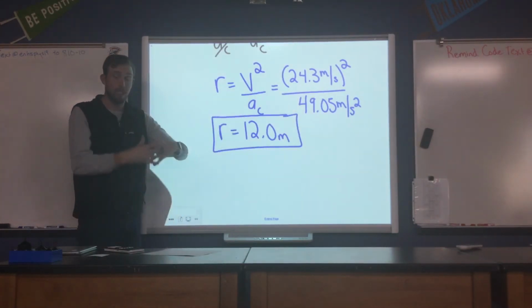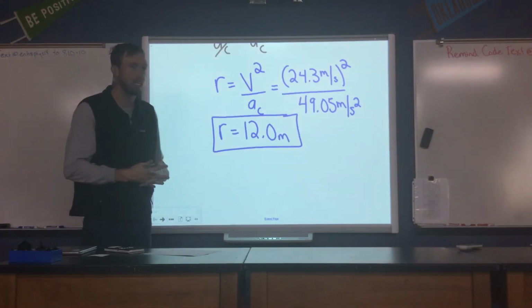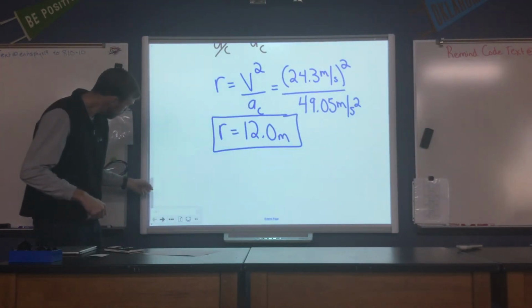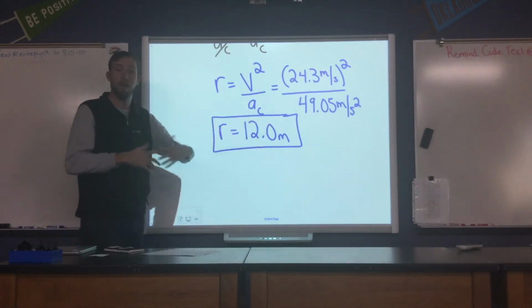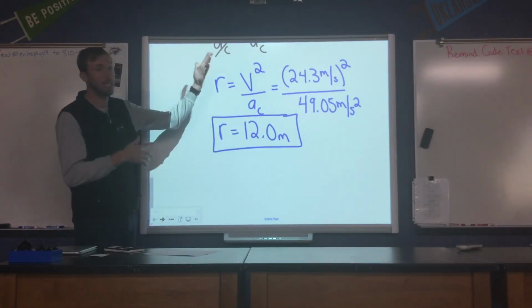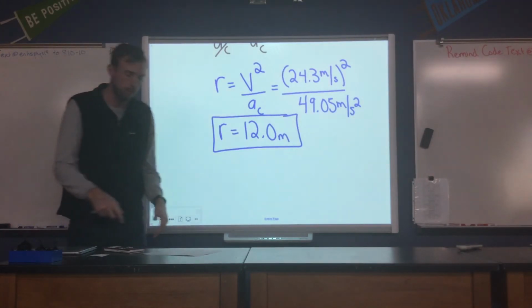And so we're dealing, again, with a roller coaster here. So there should be a sizable amount of radius to the loop. So that does seem to pretty much give us an answer to our question. We need about a 12-meter radius if we wanted our ride to be safe, given the height of our drop and the limitation on g-force.